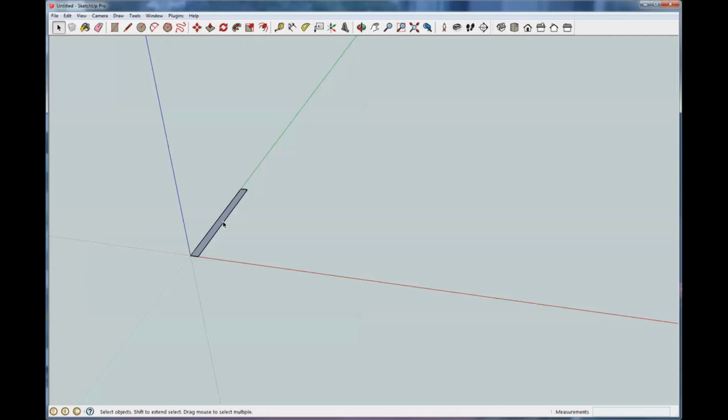The reason you need to make everything a group or a component is, if you don't, as I showed you earlier, we have separate entities. We've got our fill and we've got our bottom line, top line, side left, side right. When you touch something to that, like you create another box and pull off to it, they have a tendency to stick together. You need to treat everything like it's material that you pulled off the shelf and you're working with.